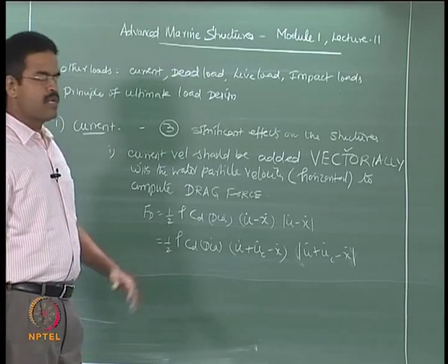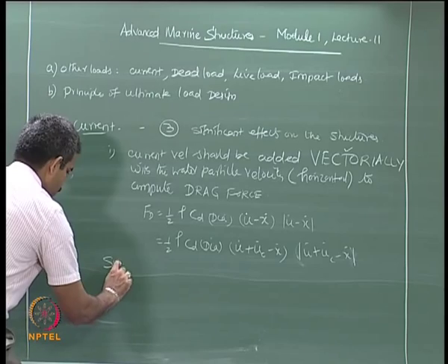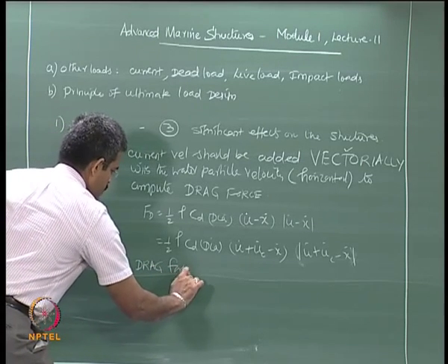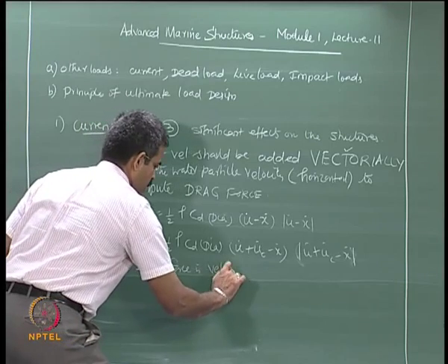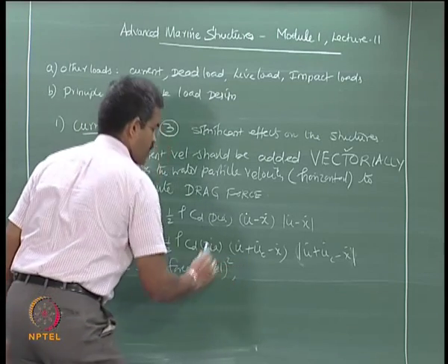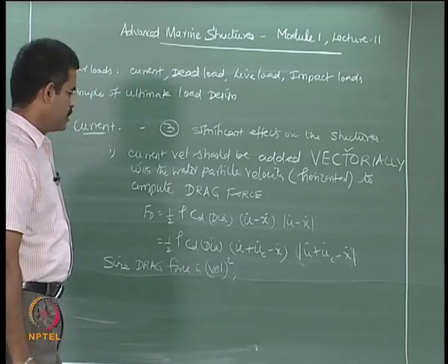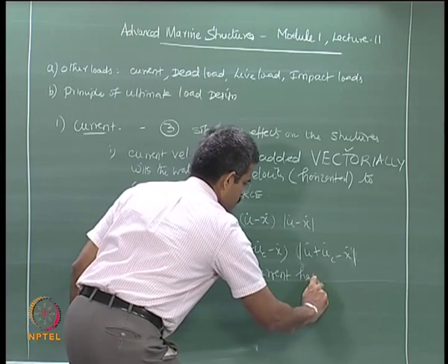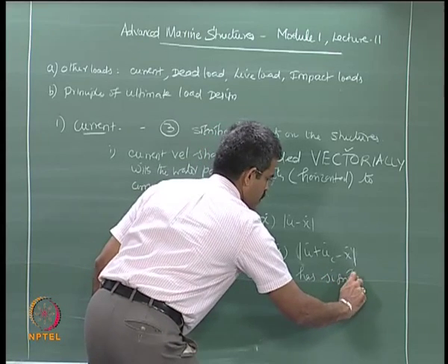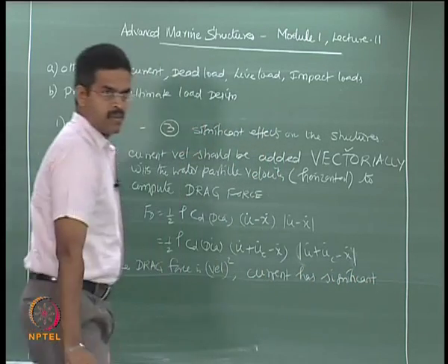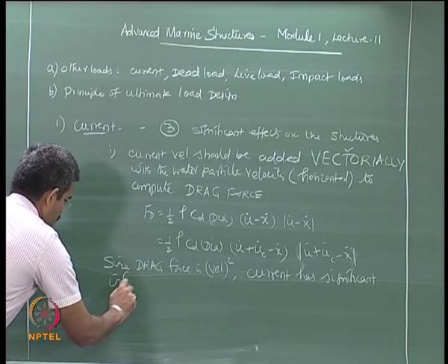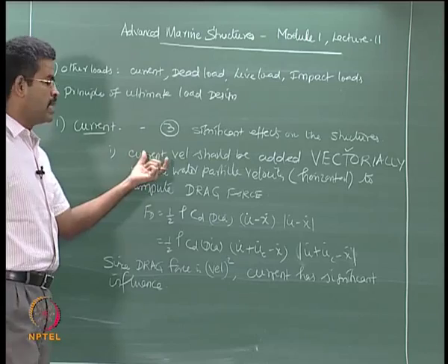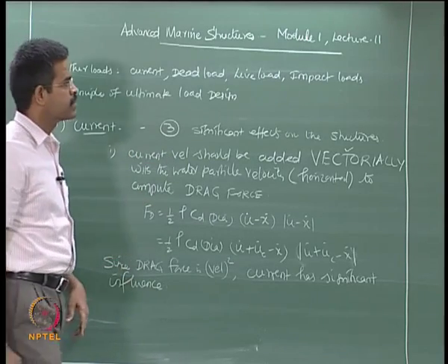So you can see from this equation that since the drag force is proportional to velocity squared, current has significant influence. So that is the first part: how do we handle current as a force?